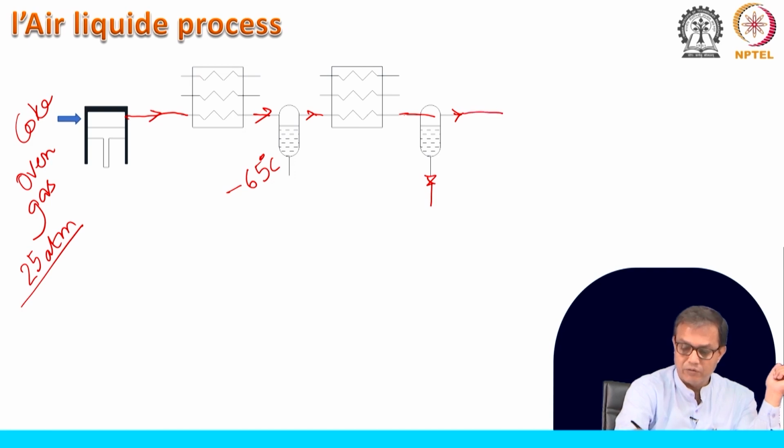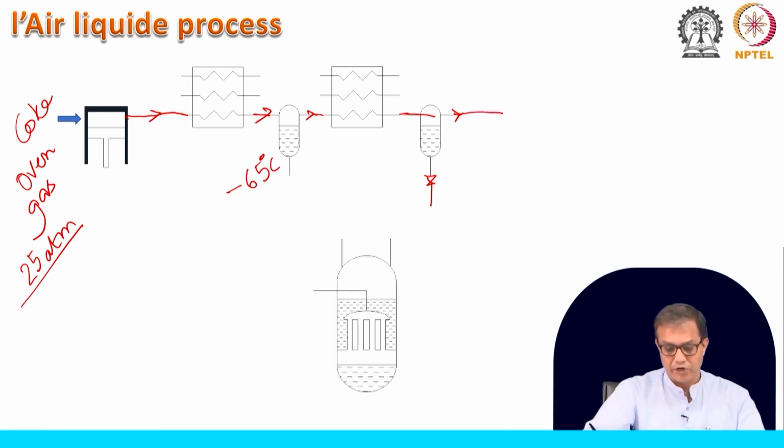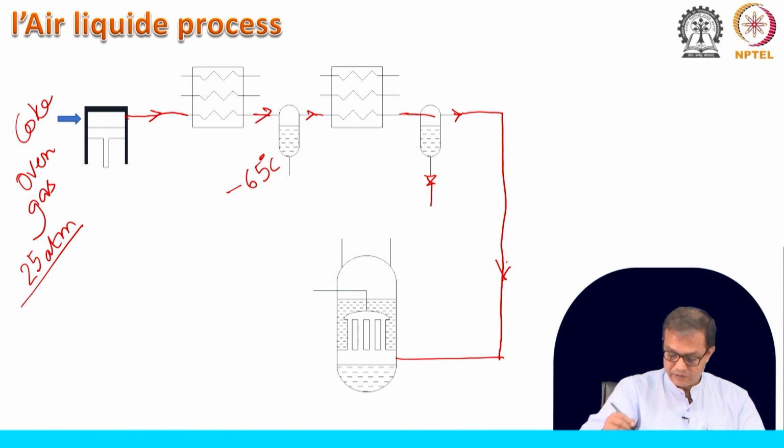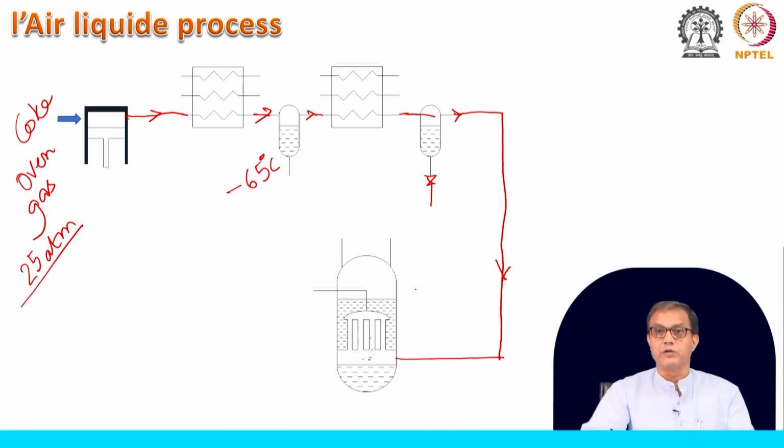But what about this compressed coke oven gas? This will continue to flow through this, and then we will put it in again a condenser evaporator. So, on this part we will be putting it as a compressed one, and it is coming over here. So, this is coming to this side, and basically it has to be cooled, right. But as we have understood earlier, this cooling was provided with the help of liquid nitrogen, but we do not want to use liquid nitrogen. So, then we have to arrange for something which will provide the necessary refrigeration here.